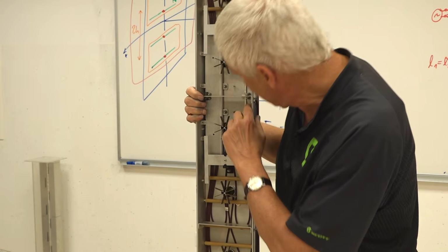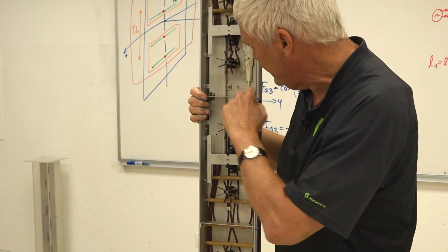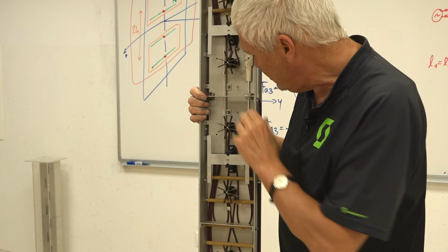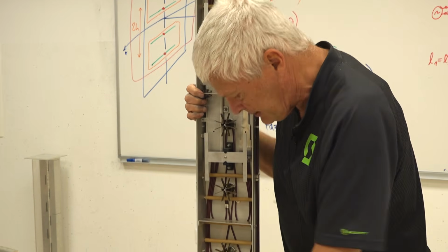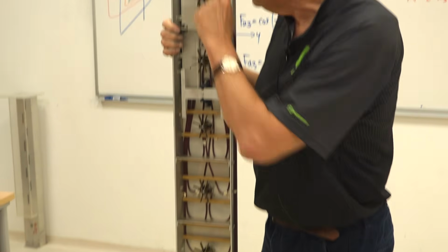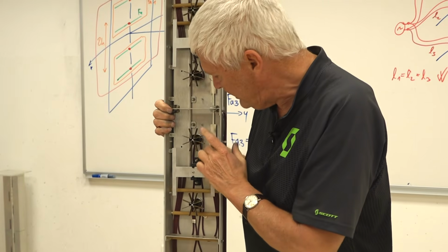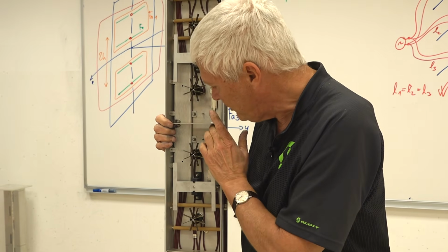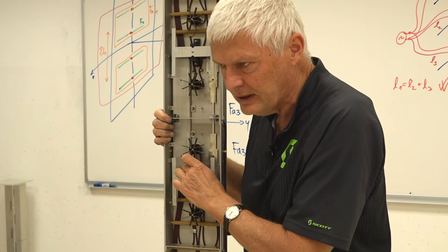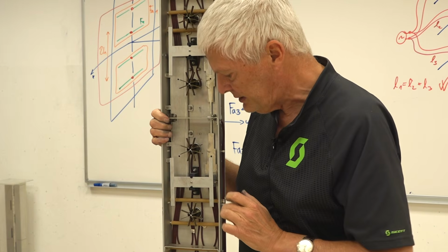You come with a single cable up here. You split this thing way out. And to get out of the 50 ohms of the supply cable here that comes up here into 850 ohms, you have to do some impedance matching. And impedance matching is done with these quarter wavelength transformers that are covered with a piece of metal sheet here. But this is removed just to see how it is done.